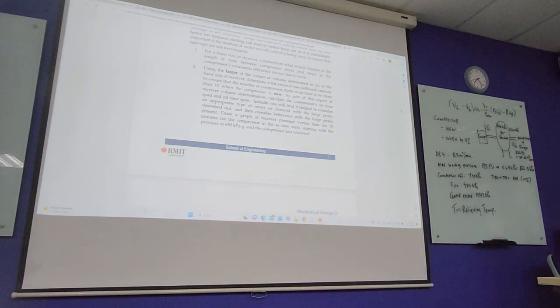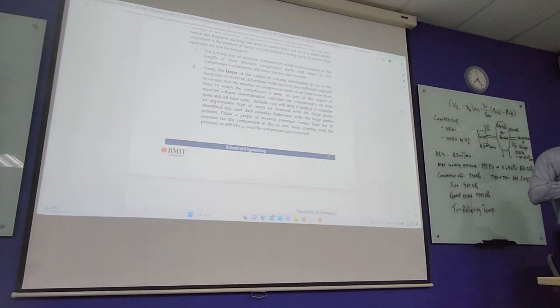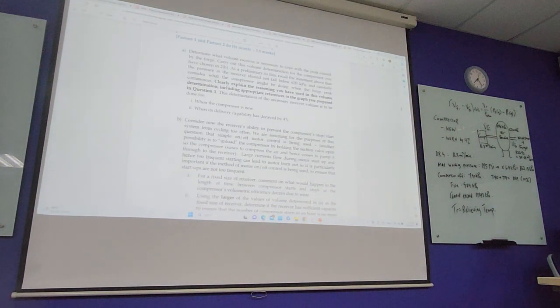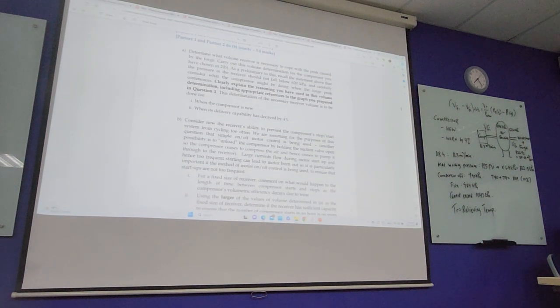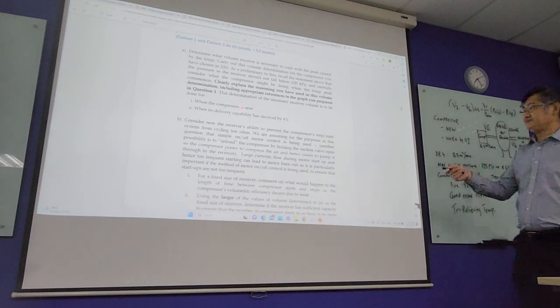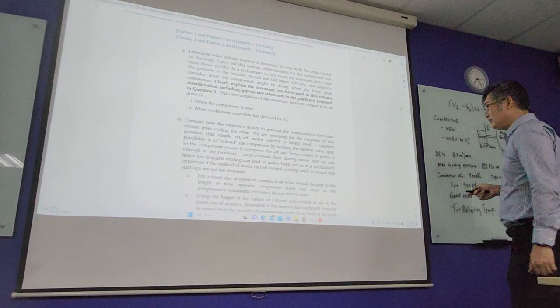Okay, so now we come to the compressor. The new compressor, remember what is the value? Your FAD, your free air delivery. 16.3, right? Okay, so another question asked is this. Assume 4%. Over here, they actually show us when the compressor is new, it's 16.3.